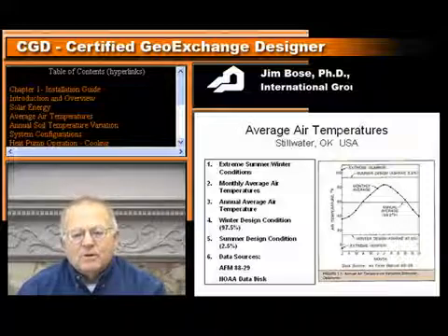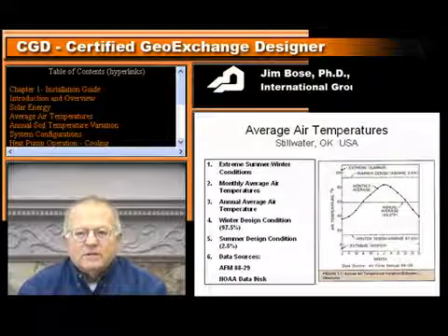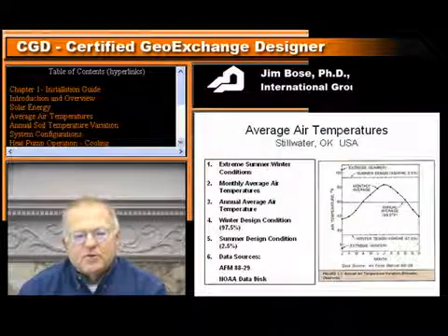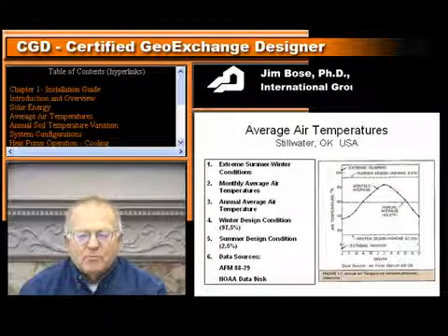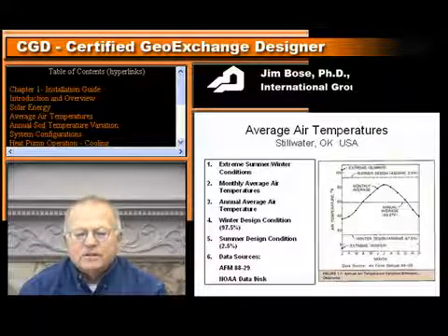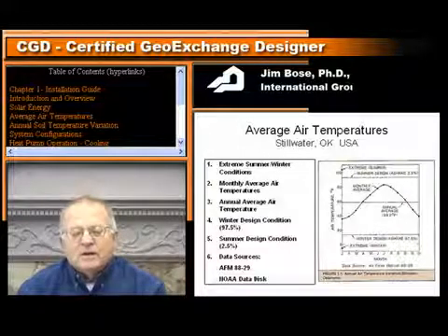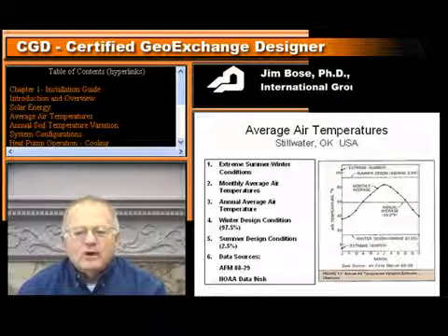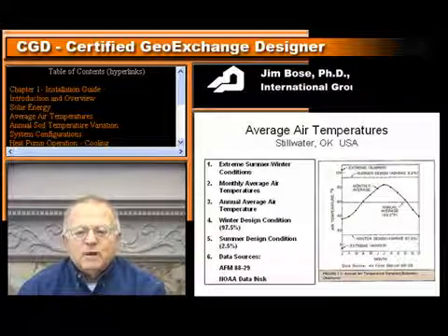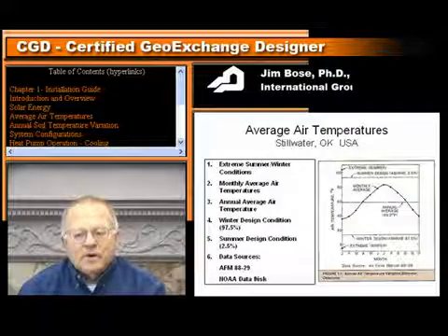In air source heat pumps, or equipment that uses outdoor air temperatures or fresh air, these are the temperatures that you might expect. Now, from a design standpoint, because those temperatures occur only rarely in the summer and also in the winter, we have what we call summer design conditions and winter design conditions. The summer design condition, ASHRAE 2.5%, says that only 2.5% of the time will the temperatures be above this design condition. In this case, it looks like that's about 92 or 93 degrees Fahrenheit.